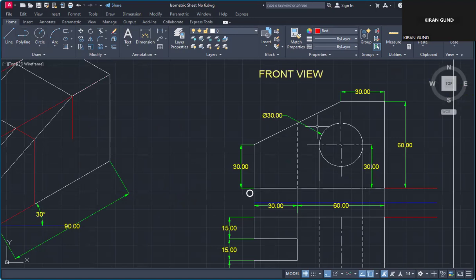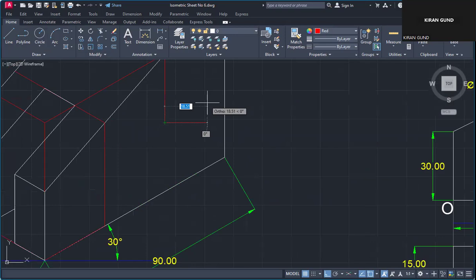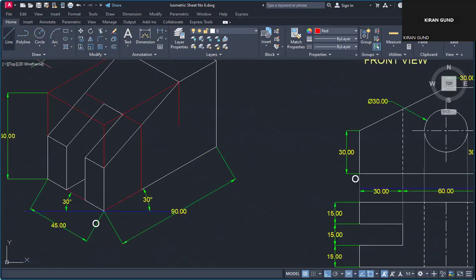Okay. So here, if we inscribe this circle in a square or a rectangle, let's say, the maximum dimensions will be equal to the diameter. So its diameter is 30. So we have to draw a rhombus of 30 by 30 millimeter dimensions on a right surface. So how to draw it?